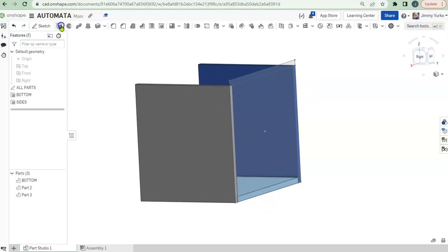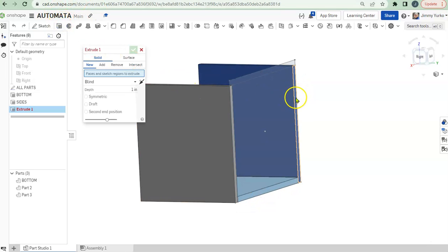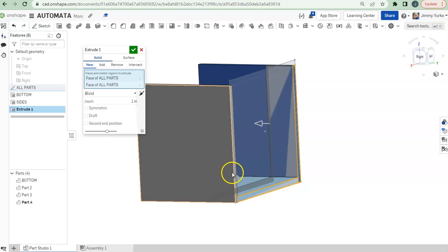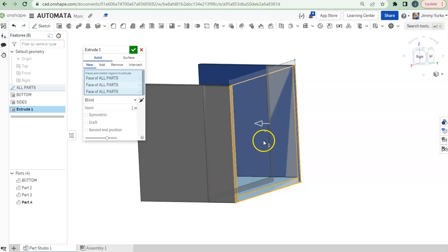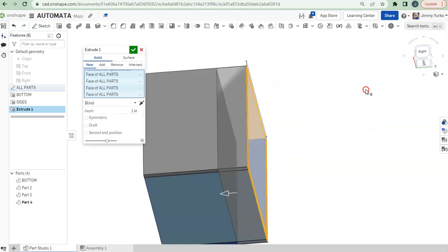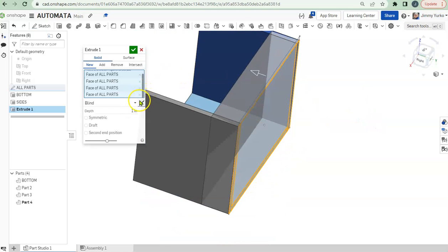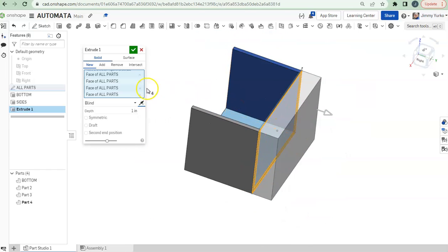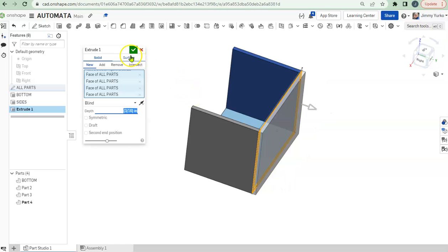So we're going to hit the extrude button, and I've discovered that grabbing the skinny rectangles first, and then grabbing that works best. And of course you can see that my direction arrow is pushing it into the material, so I'm going to flip that by clicking the direction arrow the other direction. And as the note told us, all parts are 3/16. That includes the back. And let's go all the way to the back.